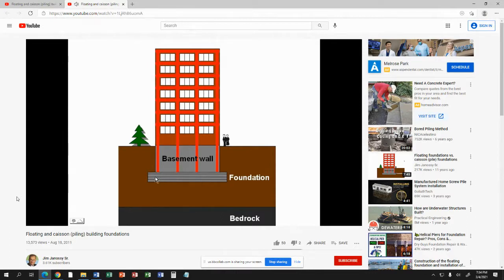The purpose of this foundation is to spread the weight of the building evenly. If these steel members just poked into the ground, they would sink. They don't have much surface area, and they would just sink right into the ground. So the foundation had to be broadened, and finally John Wellborn Root came up with the idea of having a foundation that was continuous, perhaps even spread out past the edge of the building, so that somehow the entire weight of the building borne by these steel members would be spread.